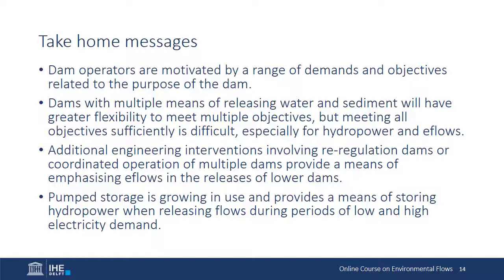For take-home messages, remember that dam operators are motivated by a range of demands and objectives related to the purpose of the dam. Optimizing dam operation for E-flows will greatly impair its ability to deliver on other objectives, and this makes reoperation difficult. Dams with multiple means of releasing water and sediment will have greater flexibility to meet multiple objectives, but even when applying advanced optimization algorithms, it will frequently not be possible to meet all objectives satisfactorily, especially between hydropower and E-flows, which both require variable flows.